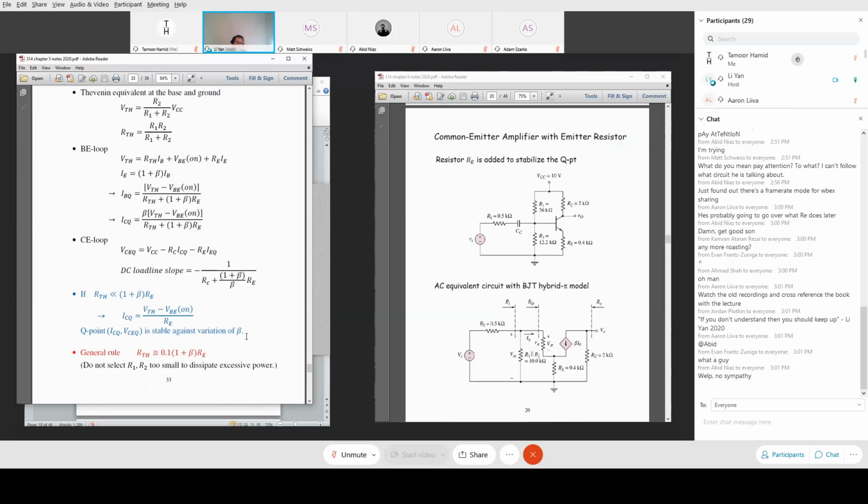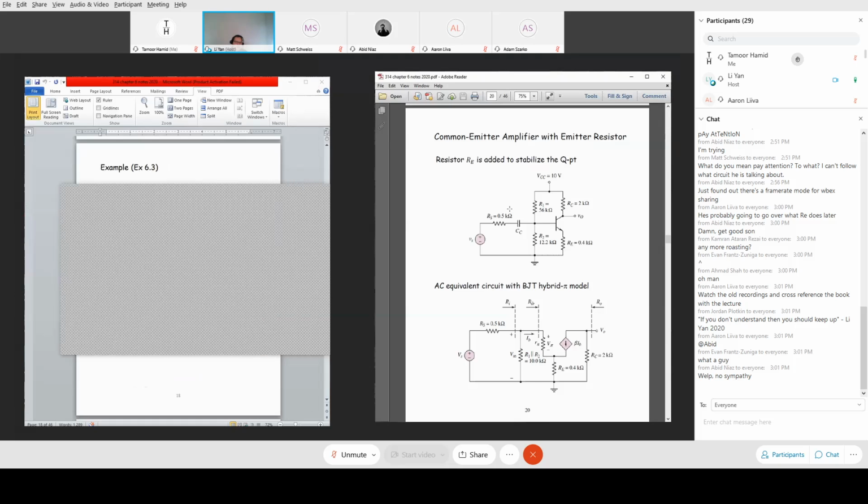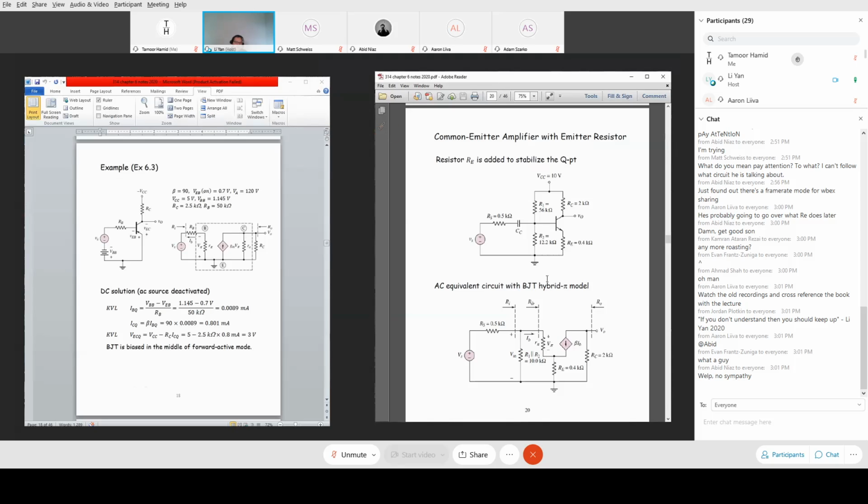That satisfied condition is the bullet in blue, and then the bullet in red. You have to satisfy something like that. That implies that in chapter 6, the circuit components will be selected such that those conditions are assumed to be satisfied. There will be a homework problem in chapter 6 saying you have to make sure, when you design a transistor amplifier, that the conditions are satisfied. It doesn't happen automatically; you have to properly select the values of R1, R2, RC, RE, and make that happen.